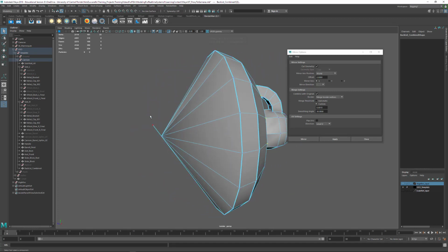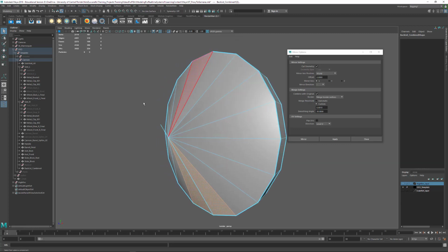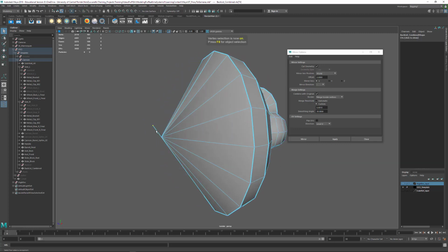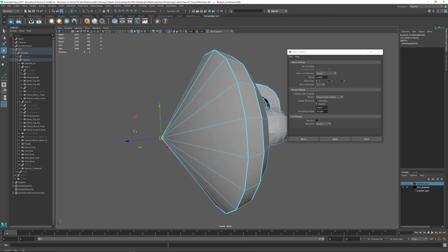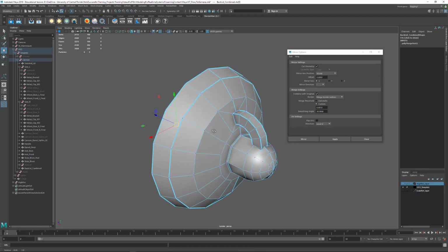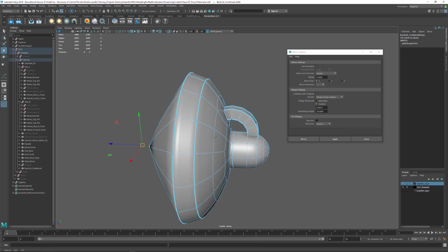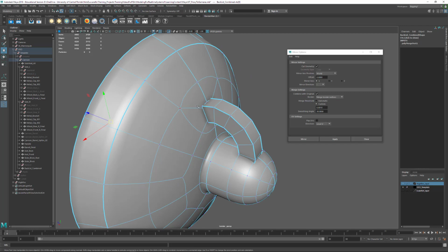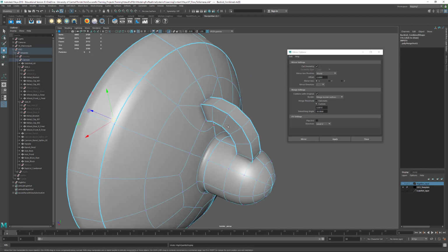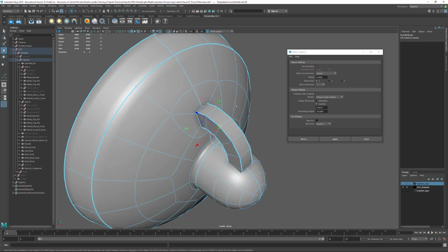And maybe I can select F9. Let's see what this is. Looks like it's just a stray vert. So I'm going to F9. Move this and snap it right here, and then I'll just shift right click, merge vertices to center, just like that. Okay, let's tap 3 for this, and that should smooth out there just like we would expect. That's fine. I'll tap 1 on this.